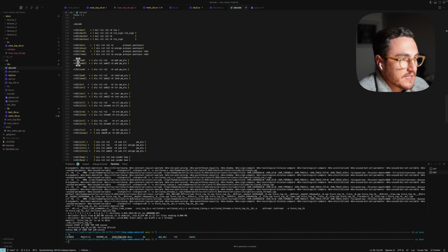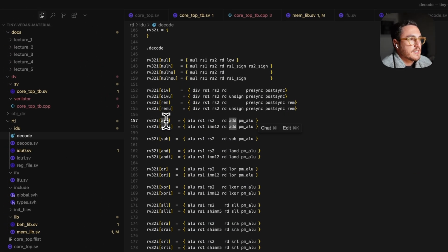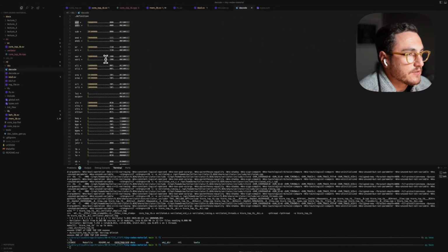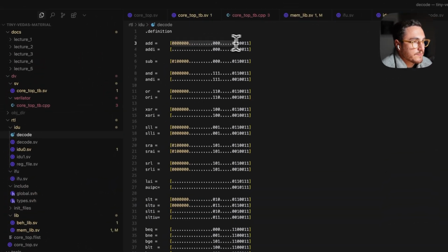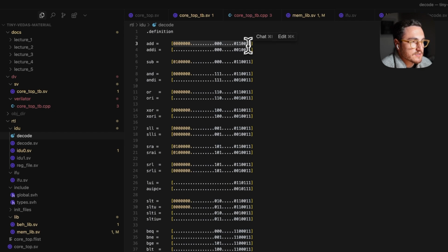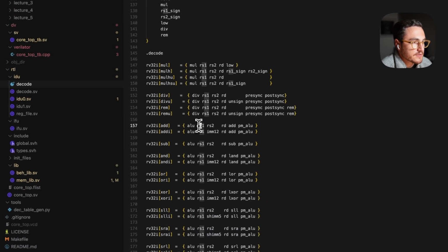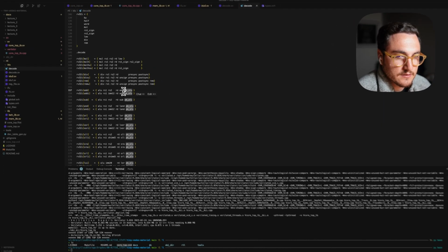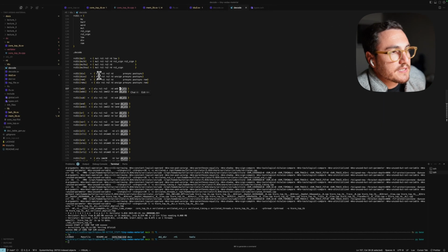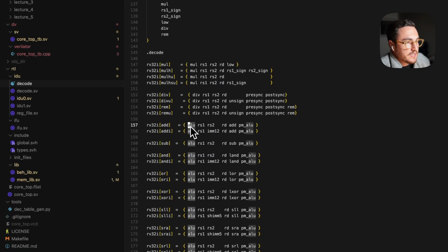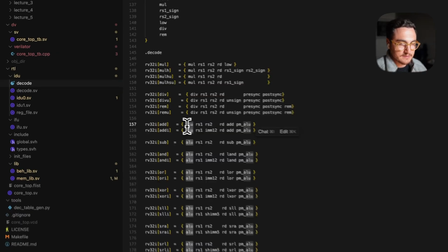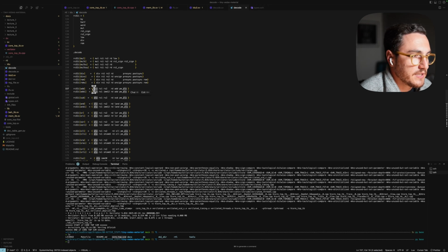And what I'm saying is, let's take the add instruction. Whenever an add instruction comes in, I look at this table and I match this line. I should set to 1 the ALU, RS1, RS2, RD, and ADD signals. Okay, so these are my decode signals, and what the ALU signal tells me is that this instruction needs to go through the ALU.